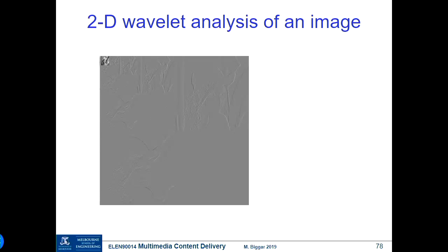So we'd be using bits to simply say that this coefficient is 0, this coefficient is 0, this coefficient is 0. We can use Huffman coding to do it more efficiently, but nevertheless we have to define all of those zeros. By scanning in this zigzag order, because the largest magnitude coefficients are up in that corner, we get to the last non-zero coefficient earliest. So maybe we only send about 8 coefficients before we're up to this one, whereas in the other case, we've done several rows. Does that make sense? Does that help?